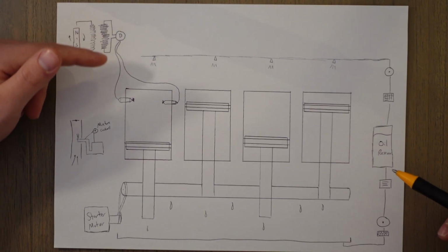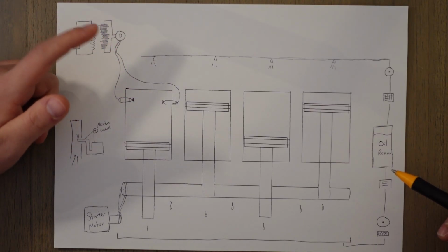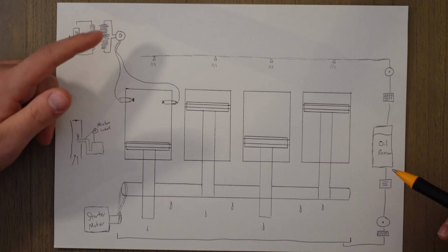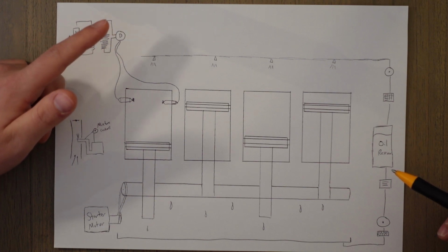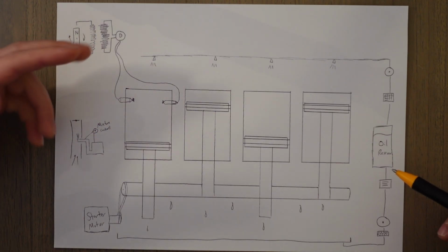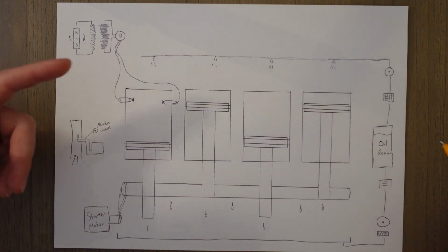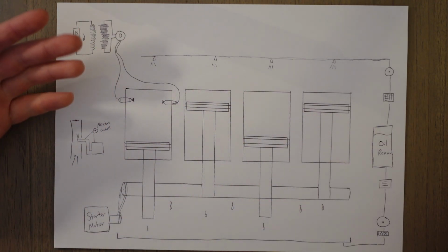Higher voltage is good because it helps create sparks in the spark plug, and a distributor is a spinning switch that sends the voltage to the spark plugs at the correct moment and means you don't need loads and loads of magnetos. You can distribute it to all the spark plugs in all the cylinders at the correct time.